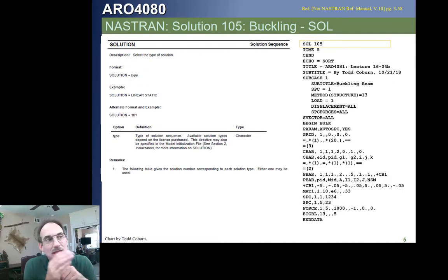But before we do, let's take a quick look at this NASTRAN deck. Let's ignore that it's got a couple different cards that make it unique for buckling, and let's focus first on just the replication that's being implemented. So you'll notice in this model, let's annotate this as we go. If we take a look at the grid card here, we see that we have our first node.